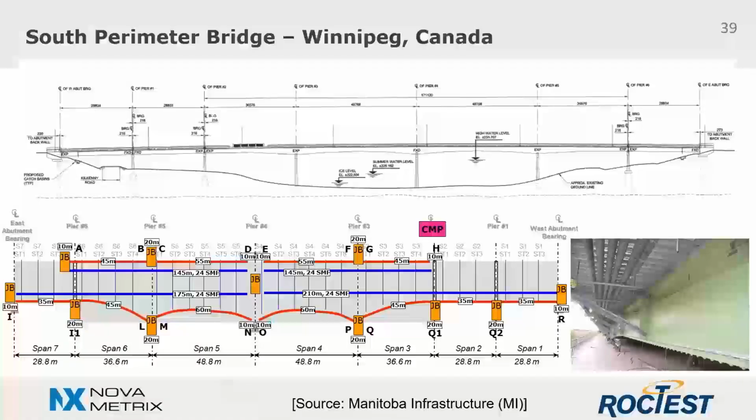So what you can see here is the lateral view of the strain sensor installation. The sensor was installed on the lower and upper part of the girder. The junction boxes that you see here were requested by the client in order to keep sufficient cable overlength to be used for immediate cable repair on the bridge. And the blue cable is a temperature and transmission cable to compensate the temperature on the strain cable.